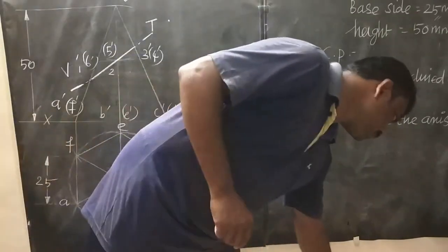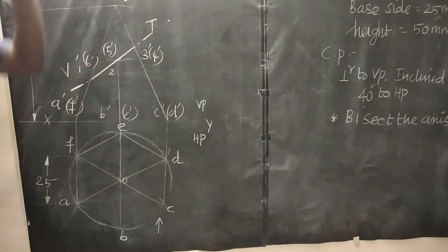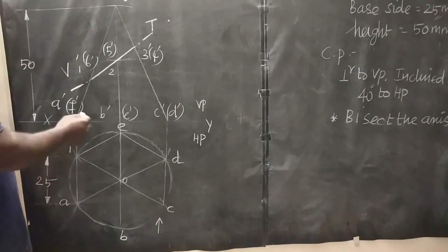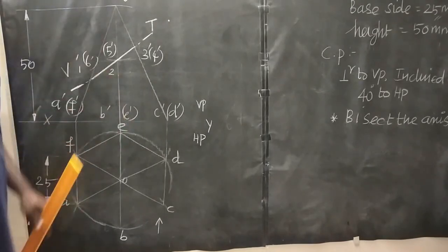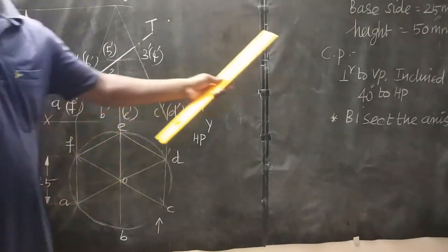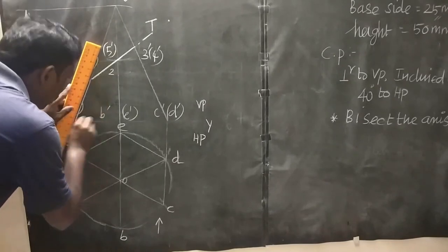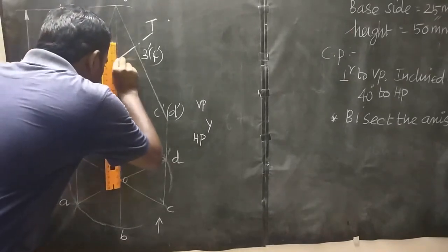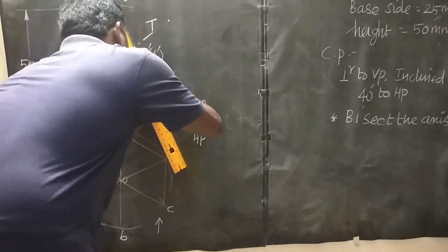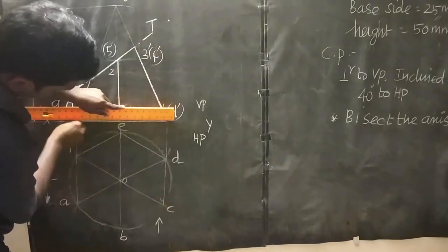After drawing this cutting plane, what portion comes above the cutting plane? Those parts are not required for our further study. Then what other portion comes below the cutting plane? Those parts draw darkly because we are going to study them in the upcoming process. So draw these slant edges darkly. Take your HP pencil. Then do this work. Then draw its base darkly.